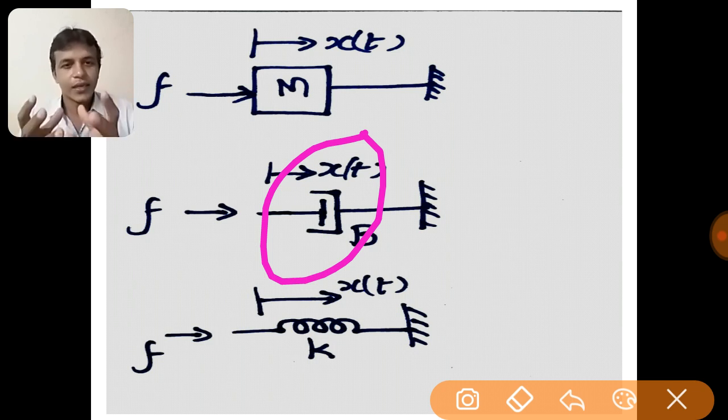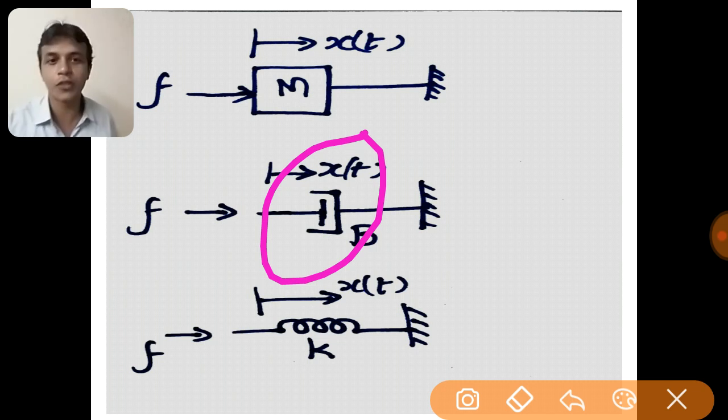So here it is giving some kind of friction. That oil, it is giving some kind of friction. It is opposing the movement of the coin. Similarly, this dashpot opposes the sudden motion by giving some friction. So it also develops an opposing force, and the opposing force is due to viscous friction, right?